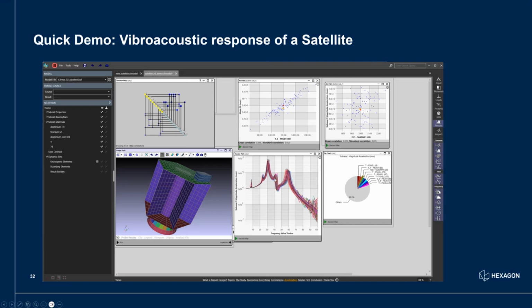For example, again, I'm dwelling a lot here. I'm asking a lot of imagination here. But if this is the response, at a certain frequency, we know that damping is a function of frequency. So it's not easy. Right from the start, you typically define a certain damping function that is flat all across the frequency. But in real life, it's hard to match. Maybe you get this peak right, but not this other peak. This could be because there is a frequency damping effect that needs to be tackled. And you could use robust design to automatically adjust that damping to meet a certain target.